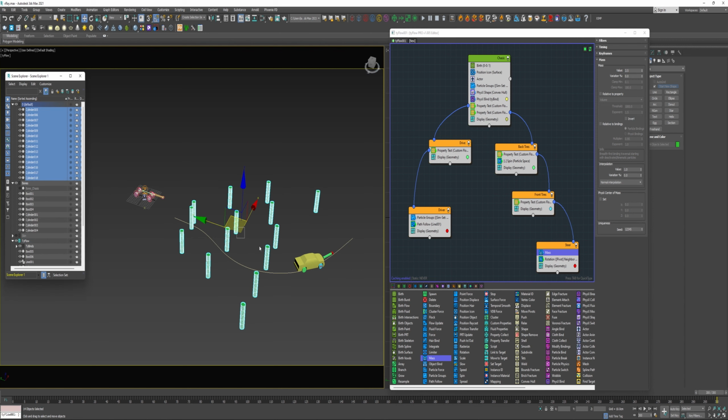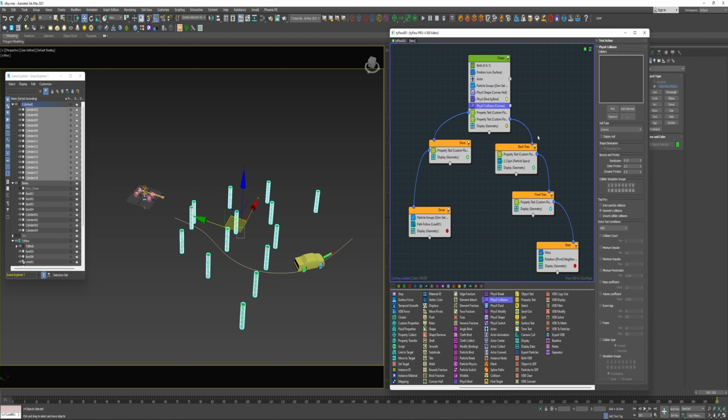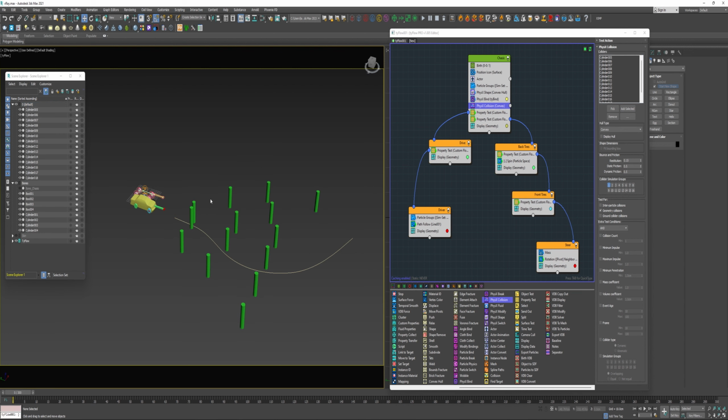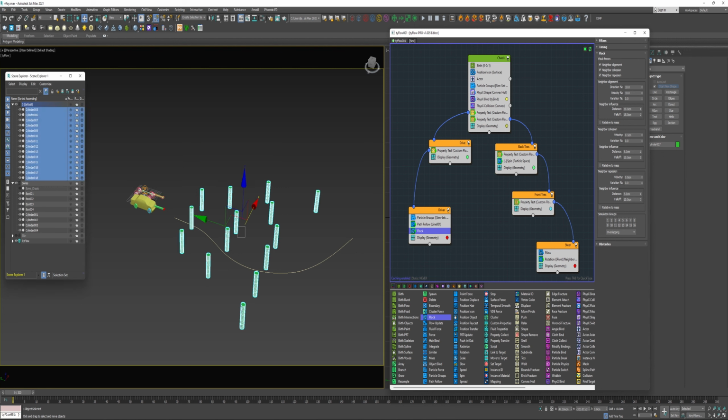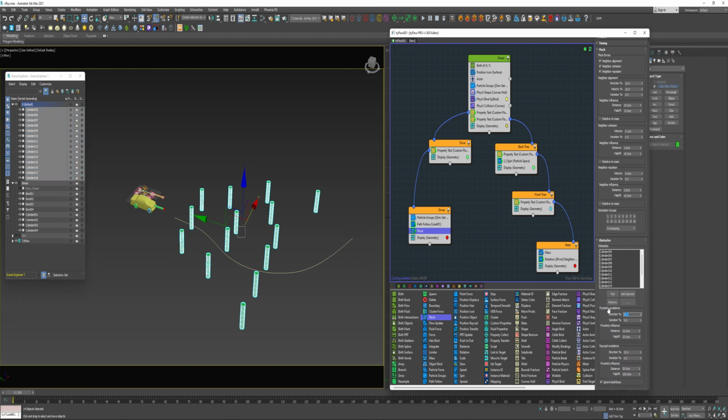and from here I can easily add interaction with scene geometry, such as if I were to drop a physics collision in this chassis event above the property test and add these cylinders, enable simulation group 1, so now if I drop a flock operator into the driver event, come over here to obstacles, and I add these cylinders, and I increase this direction to something like 45 and give it a 20% variation.